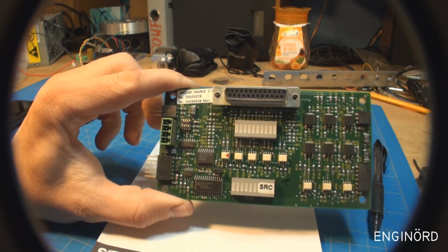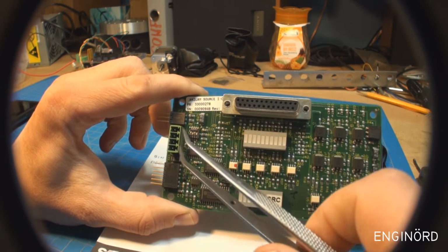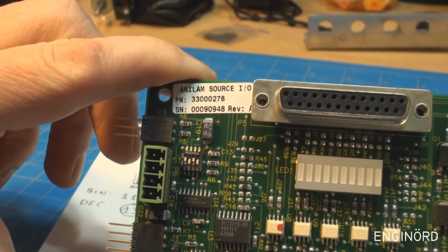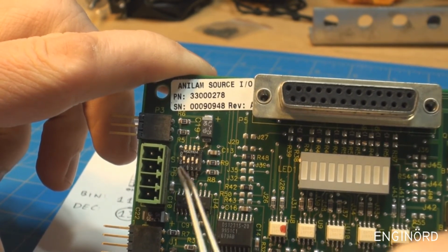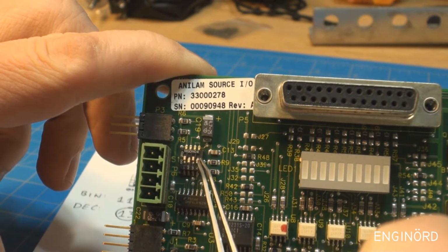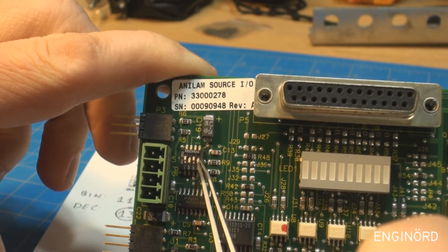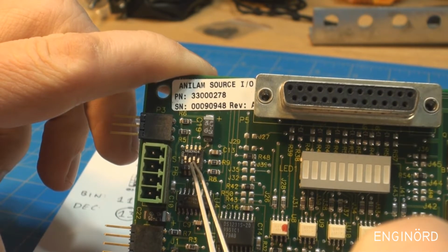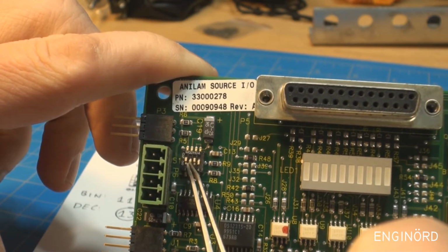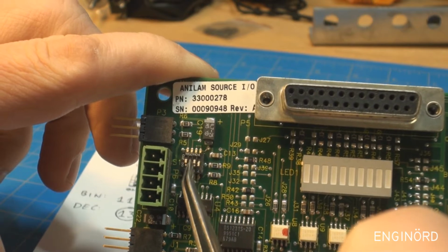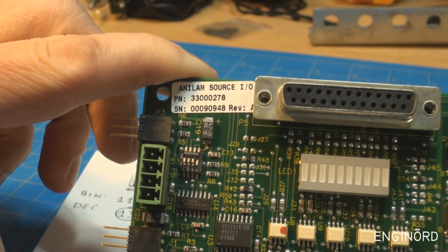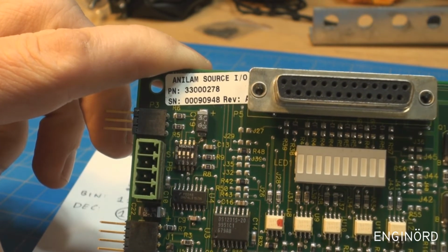And so the coding goes by these little switches here, these little dip switches. I'm gonna zoom in on it, and you can see that it is numbered 1, 2, 3, and 4. Right here, number 4 is down, 3 is up, 2 is down, and 1 is up. And actually 2 has to be up, like so. I pushed it down because I wanted to demonstrate the failure and why it is not working.